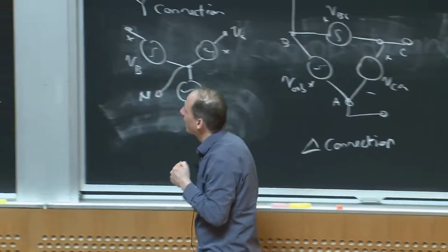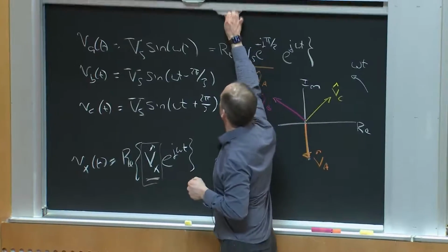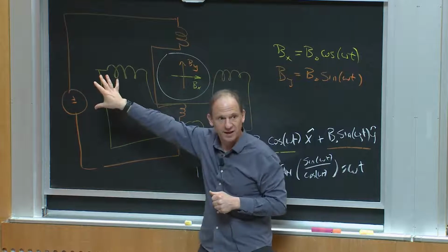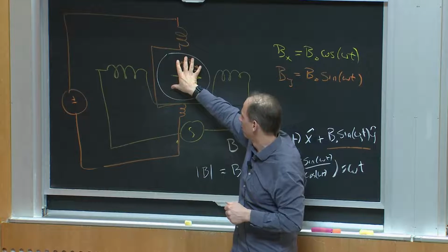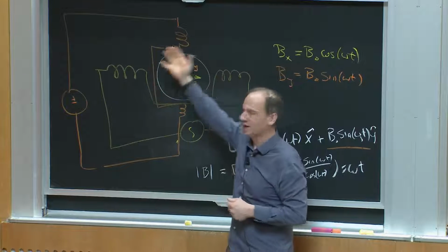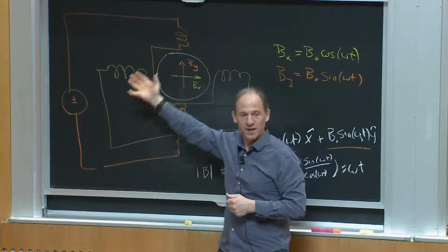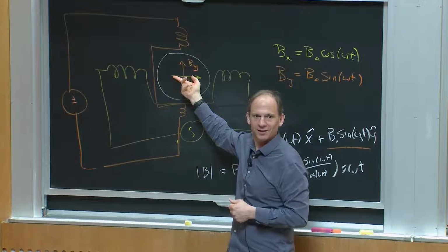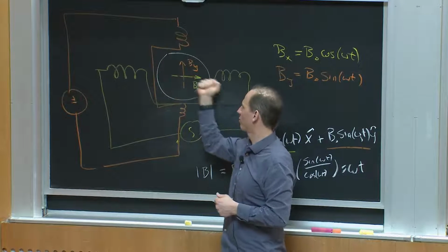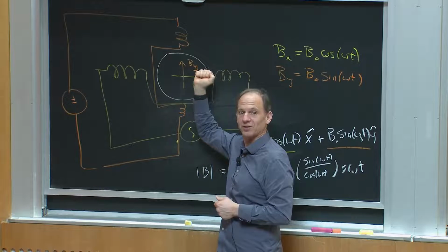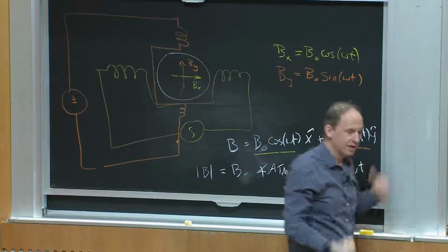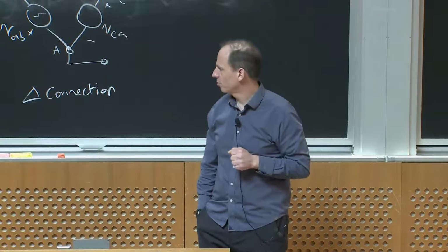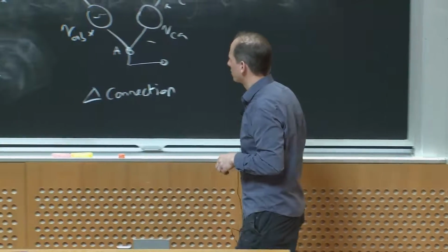I've already shown you one, actually, and that is that because I can create a rotating magnetic field, if I only had a single phase and started misaligned with my rotor, I could get it going and it would spin. I can transfer energy that way. But if I started out aligned, it just would never start, right? It would just sit there. Because with single phase, I can only generate one physical direction, okay? Whereas with polyphase, I can generate multiple directions. So that's one reason. That's a 0th reason I might do it. But what's another reason? Let's consider power transfer, right?